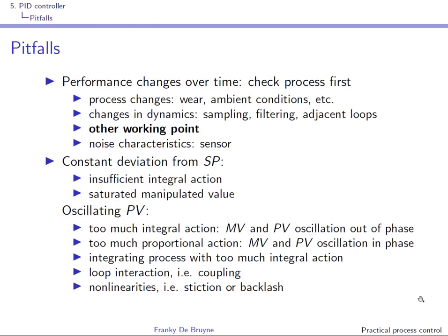Well, let us look at some symptoms that could be indicative of problems in control loops. Let us first look at performance changes. They could come from process changes, and if they do, the changes will probably be slow.